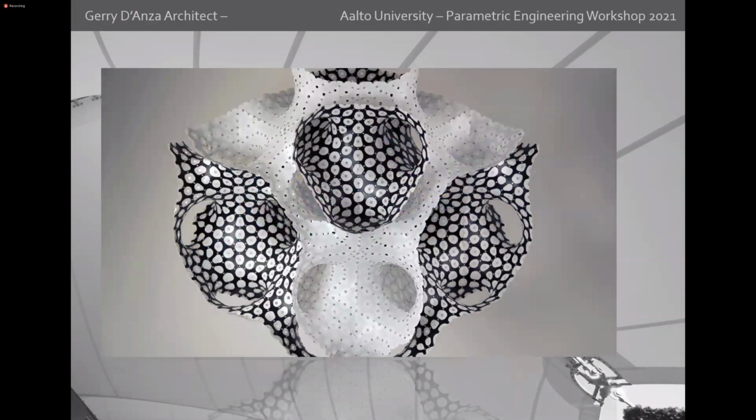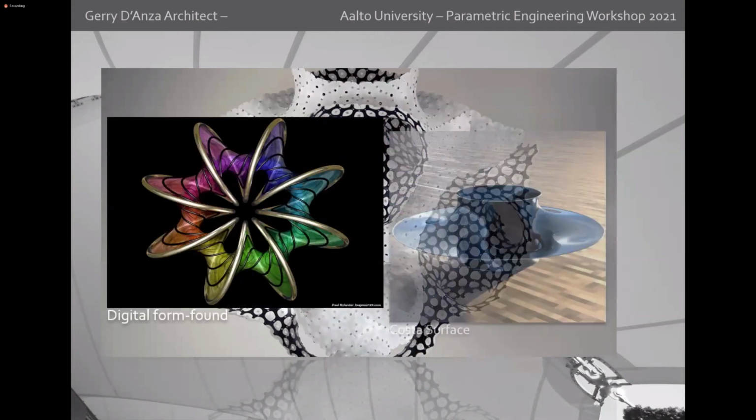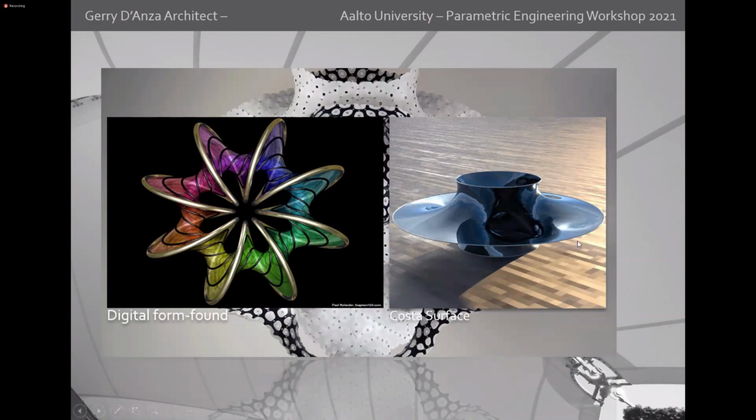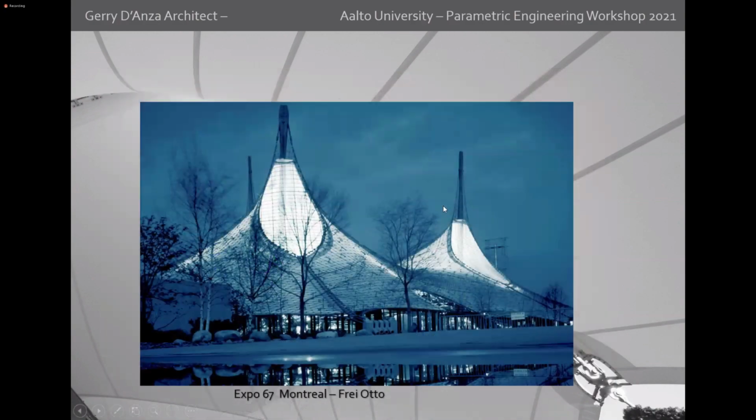And these are mathematically generated, computer generated minimal surfaces. On the right, this is a Costa surface generated with the update reference strategy. So clearly, it's up to you, it's up to the architect, if he wants to use minimal surfaces or not. Basically, what happens in reality is that the minimal surface would be the best choice from an engineering point of view. But it happens quite often that when it comes to designing a tensile structure, we have a lot of constraints.